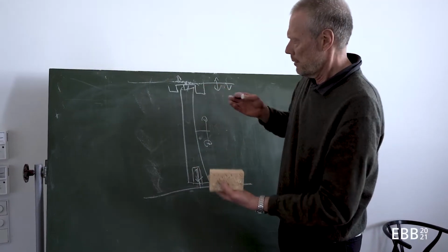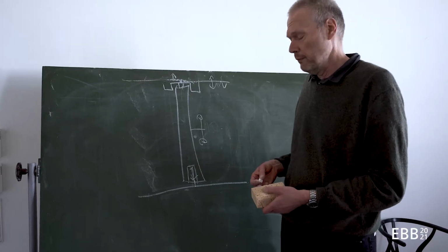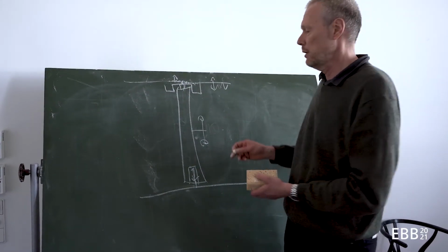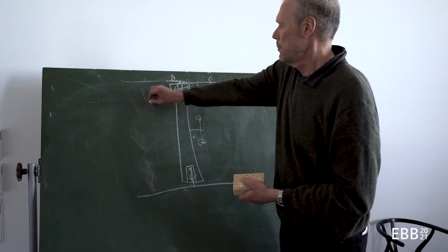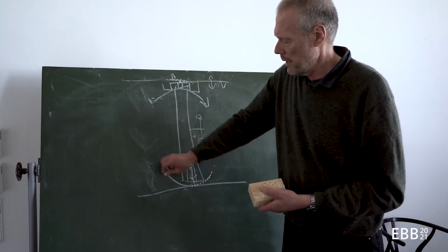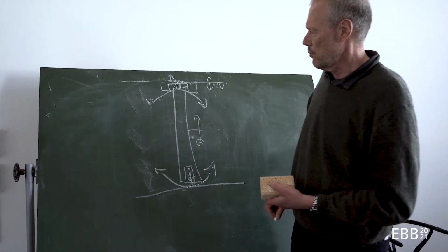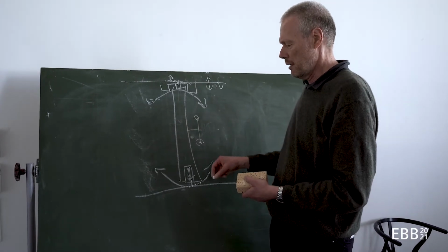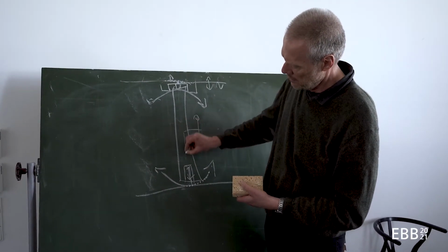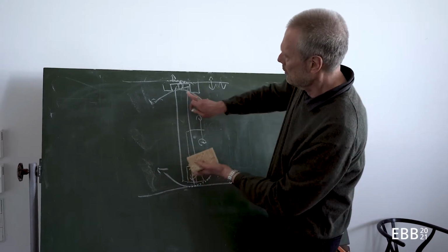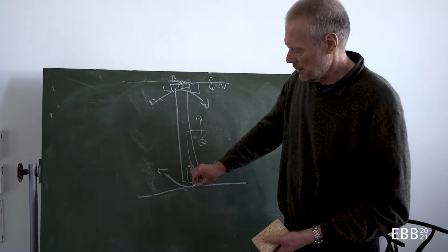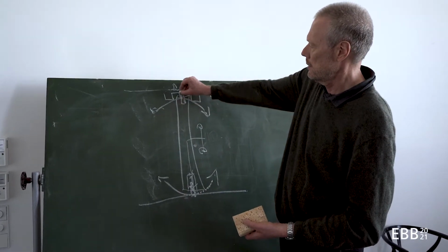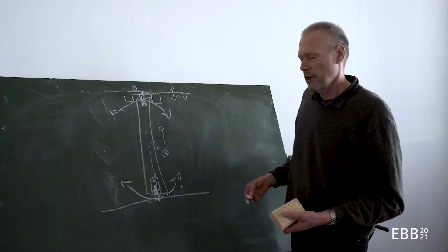In the case of the sliding wall, I need special seals at the top and at the bottom, because I want this to be airtight. And so what is currently done is to have a sort of operating handle, and with this operating handle I might drive out particular seals that then achieve airtightness in the driven out position.